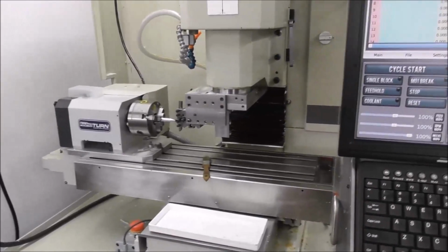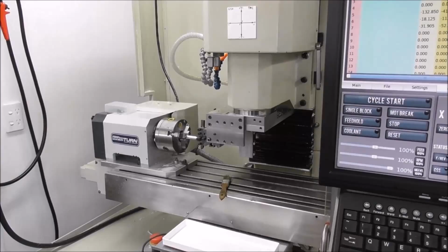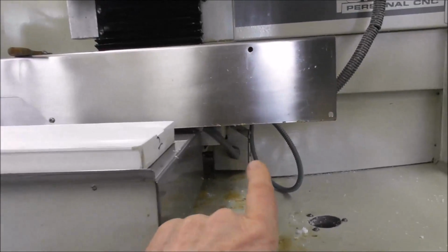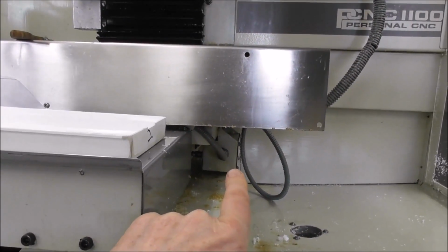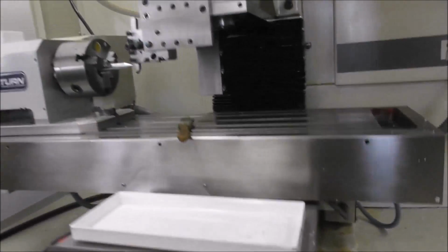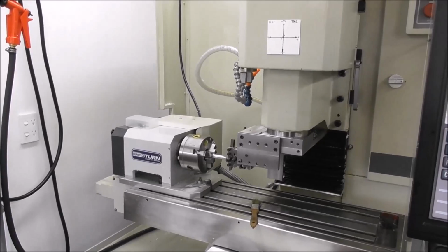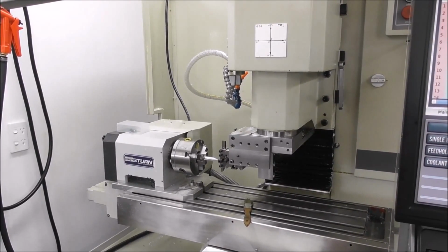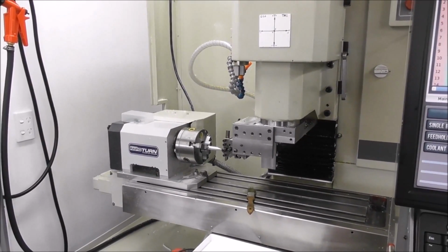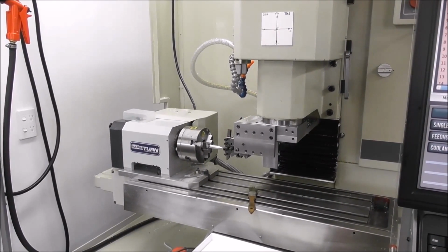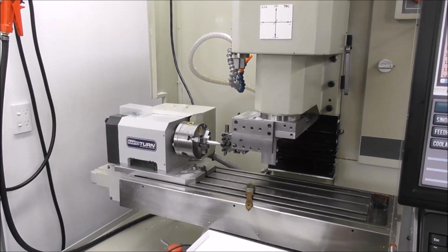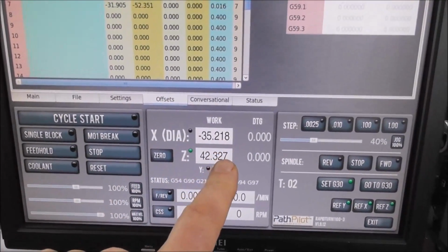Just reiterating again, so if you come in the morning and you run your first part, there might be a thermal change, but there might also be a change due to a homing error. I mean, most of you will know that the homing micro switches are just basic roller operated micro switches, and they will only re-home or re-reference to within 1 thou or 2. And you might have got a bit of swarf on the roller that intermittently changes the homing position by 5 or 10 thou. And so again, you want to change all of the tool offsets to accommodate that homing error, but you don't want to change the relative difference between the tool offsets, so you would make that change via the main DRO.